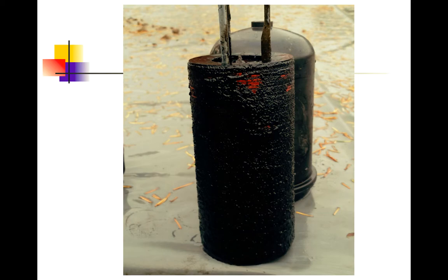You'll notice the red discs that are apparent on portions of this. That's where most of the water is getting back flushed through, and it's cleaning the internal portions of the filter, not so much the external part. If you were to open the filter up and you see this, probably wouldn't be a bad idea to clean it. On the other hand, if your pressures are what we've already shown you, that system's doing what it's supposed to do, and it's functioning as intended.